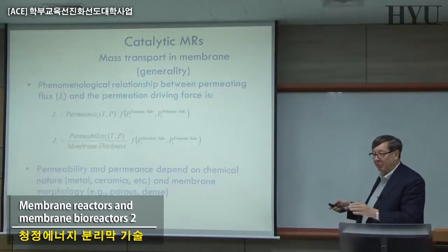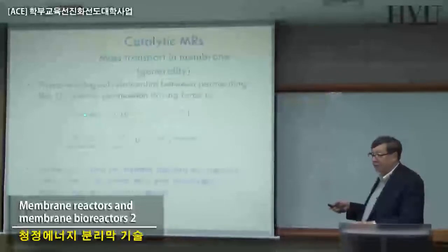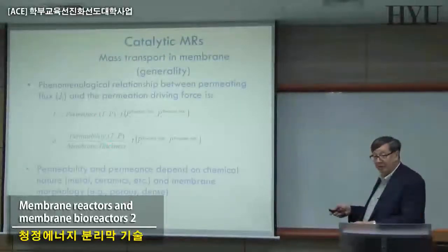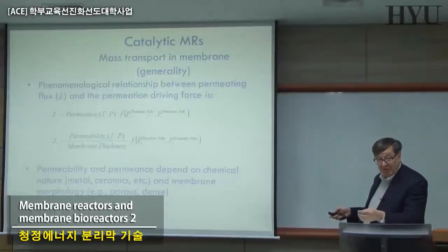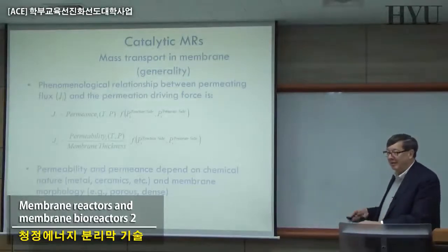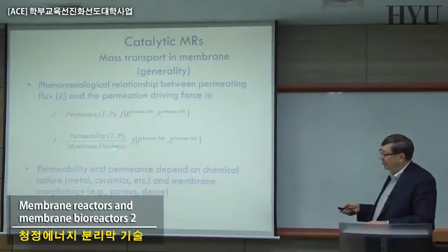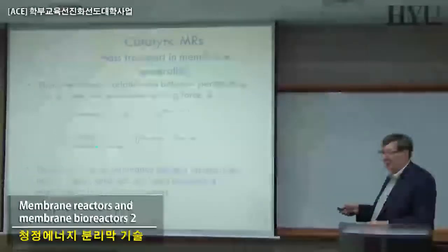It's a term of proportionality between transmembrane flux and driving force. But the dimensions of the permeance and permeability are different. Numerical values can be different. So don't use the same numbers if you don't understand what you're talking about. And all the difference is basically here.